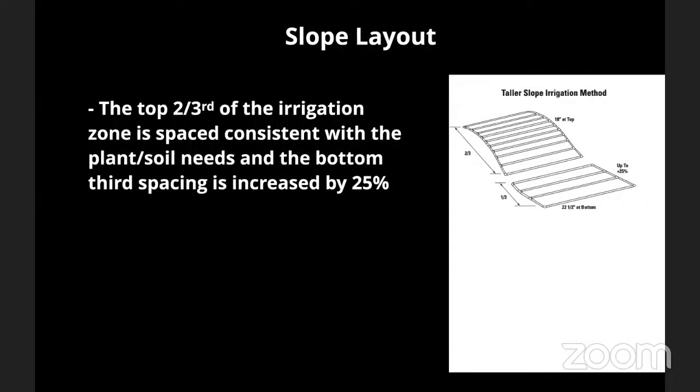And so for the person who asked about slope, here's the slope layout generally. If you have just a gentle slope, you don't need to worry about it. But if you have a steep slope, the main part of the slope you will do based on the normal recommended spacing. What you need to do with the slope, though, is keep an eye on the fact that you are not watering for so long. This is going to be on your soil types, so it's going to be site specific, but you need to keep an eye on how long you can water before you start to suspect that there's runoff along the slope.